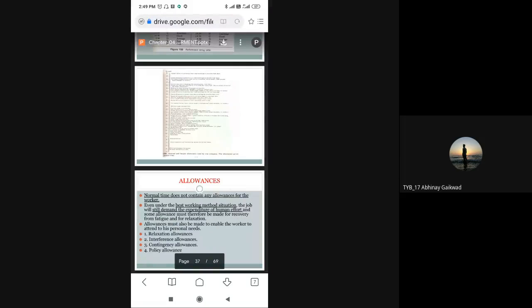Okay. In short, I would like to tell what actually happened in the previous lecture. What is work measurement? Then where we can use the work measurement, what is the application, and what are the work measurement devices we can use in the shop floor. That is very simple. Different types of clocks, digital instruments we can use for time measurements, and there are boards as well as charts. We just have to take the times while doing the job and note them in the sheet. Whatever the idle time is, that we have to measure, and on that basis we can calculate the standard times.